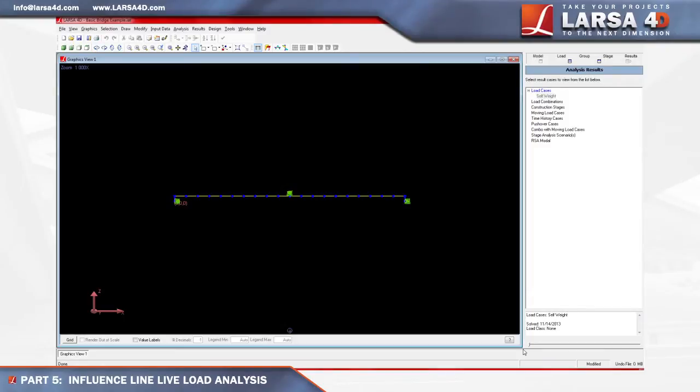Influence line and surface analysis is an extension of the moving load analysis, which uses the effects of a unit load to rapidly compute the effects of arbitrary, complex load patterns on design lanes. Often necessary to comply with bridge design codes such as AASHTO LRFD, influence-based results find the worst-case scenario out of more possibilities than can be analyzed individually.